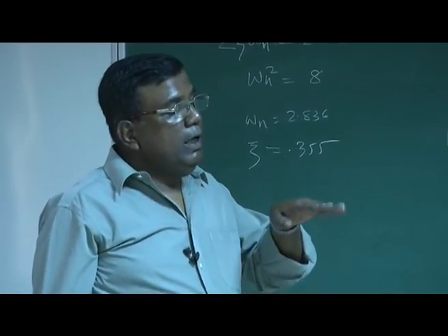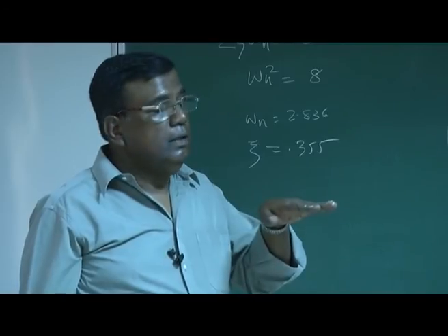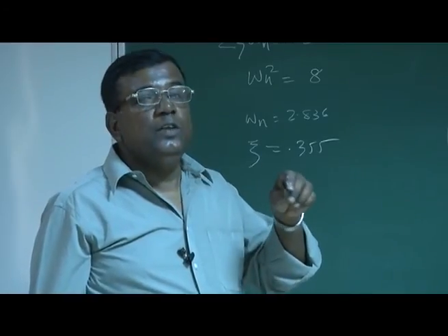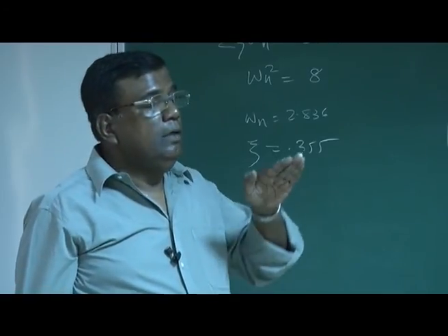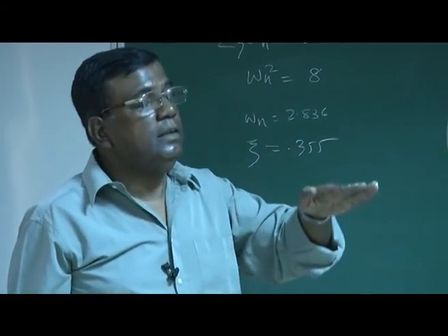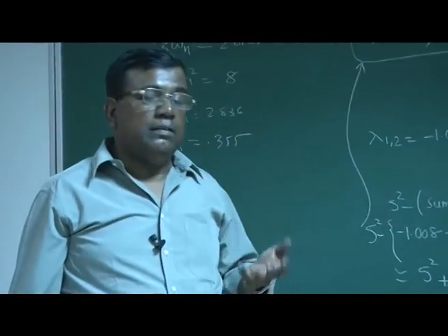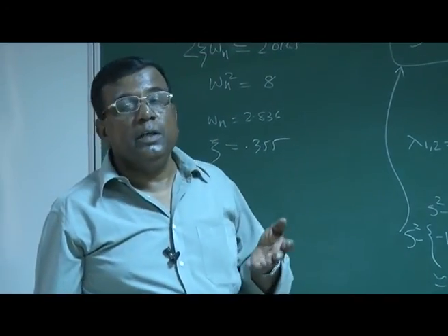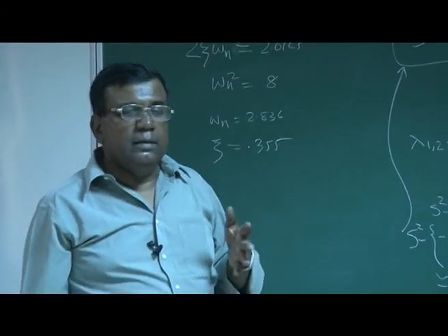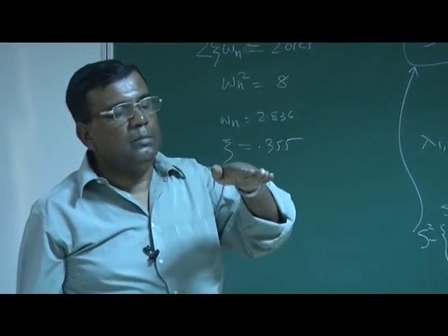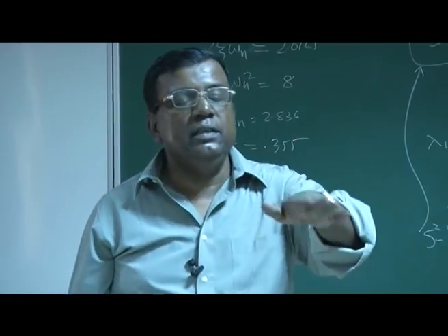In that mode, we assume that things happen so fast that the change in U is negligible. But in the phugoid mode, the long period mode, it almost goes like this, with a change in kinetic and potential energy. The classical book says alpha almost remains constant. There is a debate.